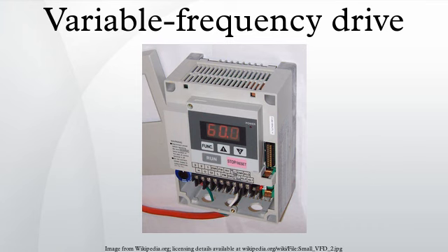cables. Dynamic braking. Torque generated by the drive causes the induction motor to run at synchronous speed less the slip. If the load drives the motor faster than synchronous speed, the motor acts as a generator, converting mechanical power back to electrical power. This power is returned to the drive's DC link element. A DC link-connected electronic power switch or braking DC chopper controls dissipation of this power as heat in a set of resistors. Cooling fans may be used to prevent resistor overheating.